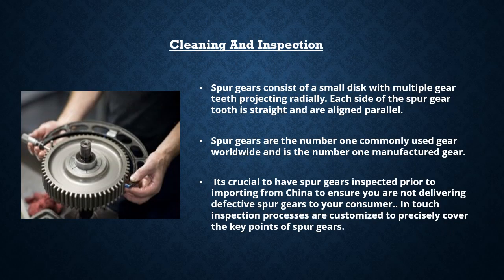After the casting shakeout process, the next one is cleaning and inspection. Cleaning involves removal of sand, scale and excess metal from the casting. All sand and scale are removed to improve the surface appearance of the casting. Excess metal in the form of fins, wires, sprues, runners and gates is removed. Inspection of the casting for defects and general quality is performed.